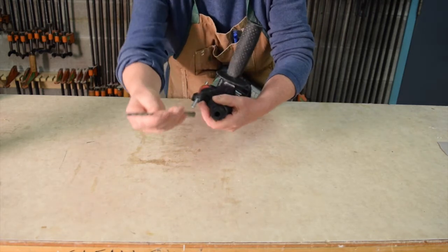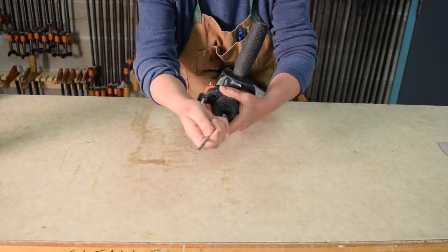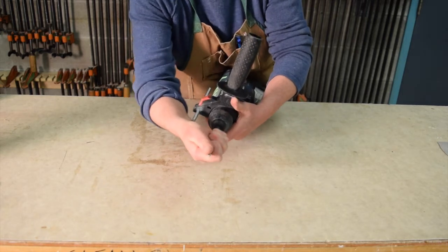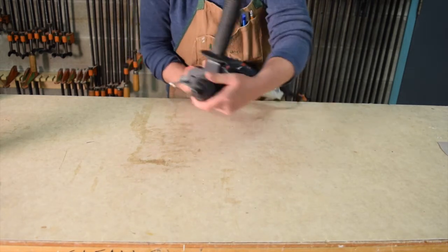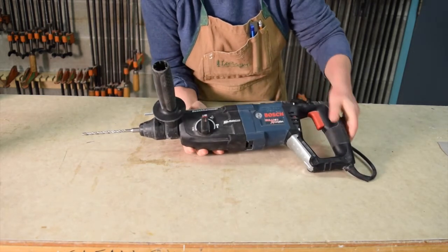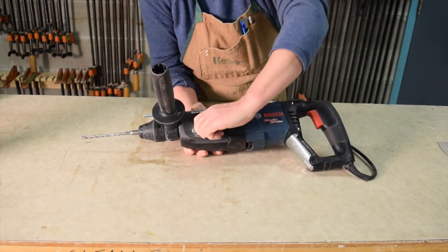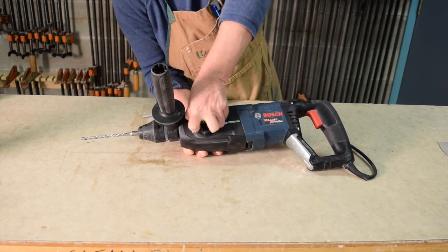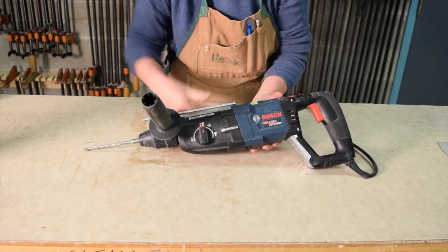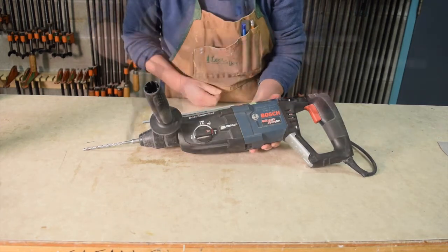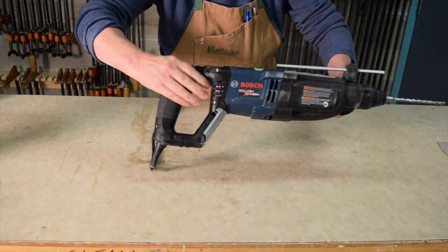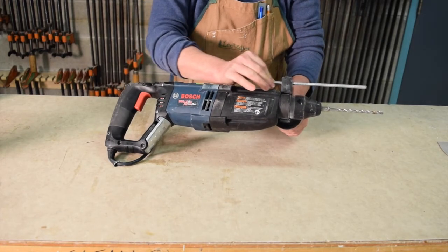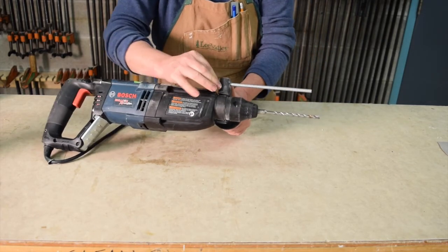We also have a hammer drill in our studio that is an SDS hammer drill. So that's just a different kind of power transmission. I find them quite a bit more effective than the standard corded hammer drills. Again, there's an option for drilling, hammer drilling, and in this case, a small jackhammer setting. There's the trigger, and there's also a depth adjustment on the top of this hammer drill.